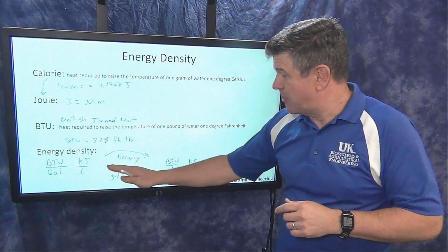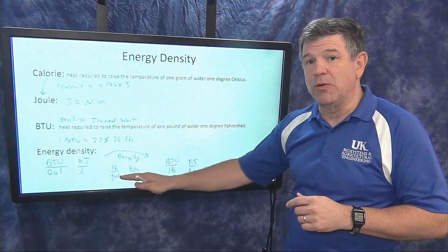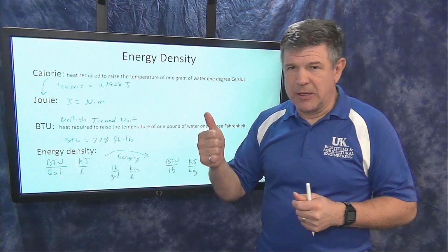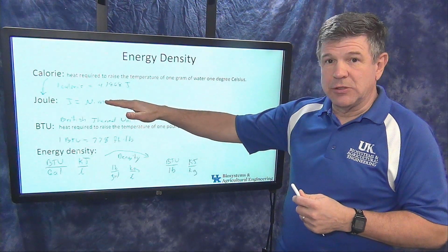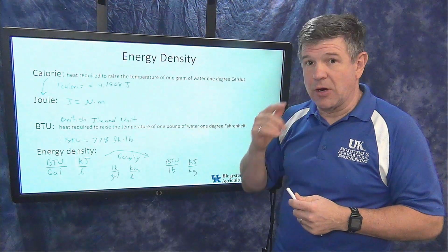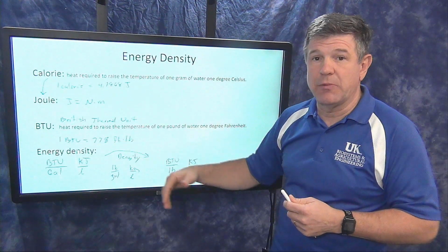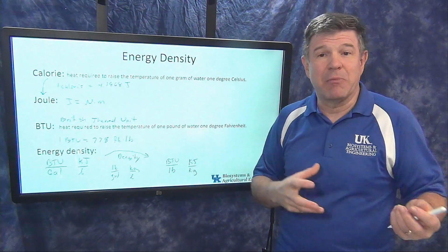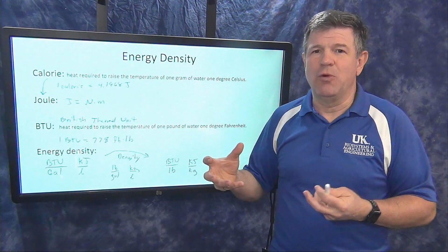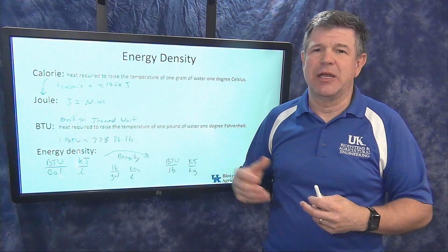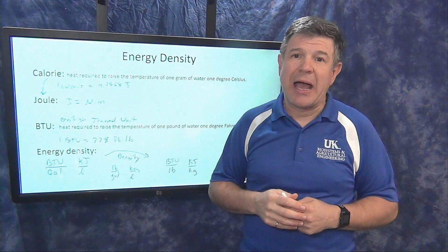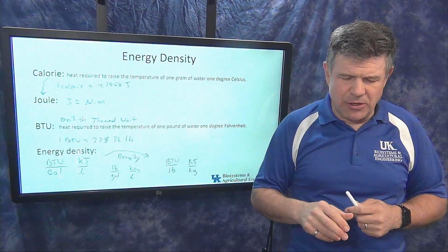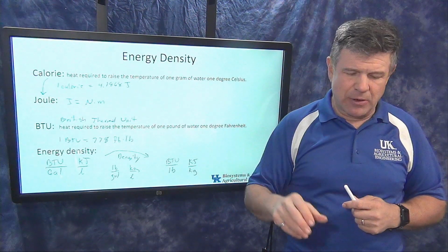Okay, so the physical density of the fuel is a property of that fuel that I'm going to need to know. Key things here, again: joules and BTUs in terms of energy, and how we can convert them to foot-pounds. I'll show you a little later how we take that to power by looking at the flow rate of that fuel, how much fuel that engine is consuming. That'll tell me the equivalent power of fuel that engine is consuming. So that's energy density. That's a key thing. We're going to come back and use that a lot.